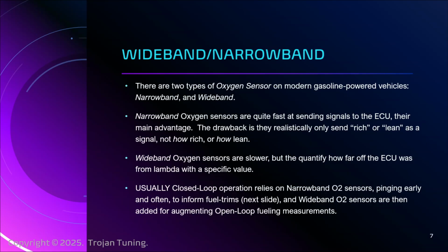You go to an exhaust shop and you get this thing welded in. And then you have an independent sensor for open loop that can tell you specifically what your lambda is, and you can compare the commanded and actual. So that's often how we have to begin.